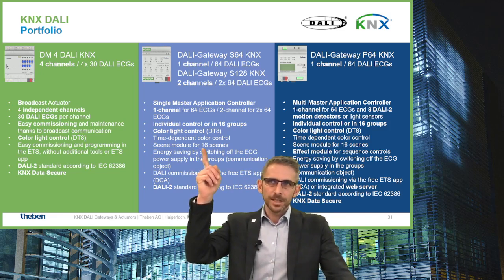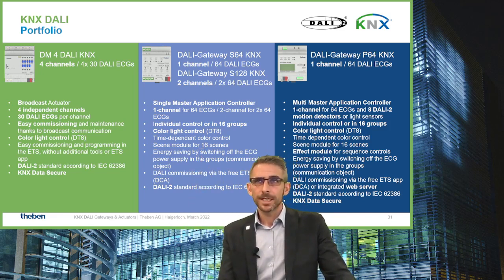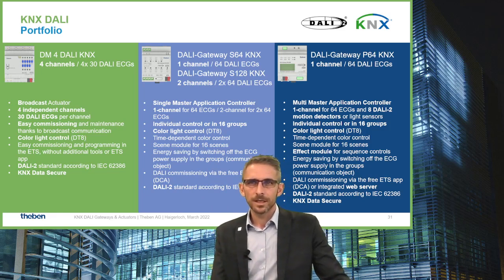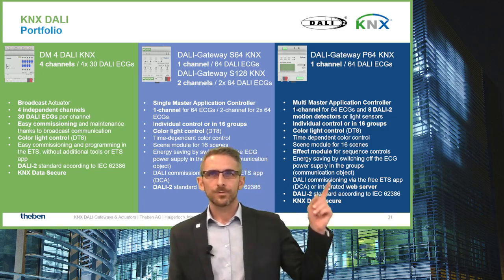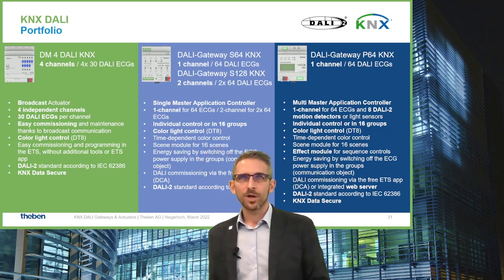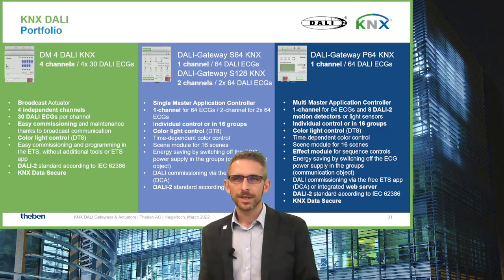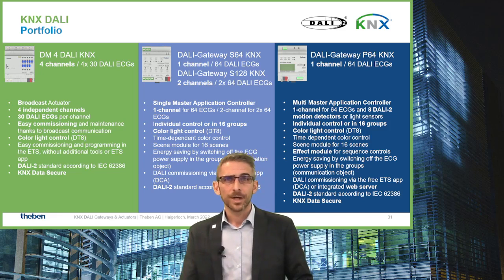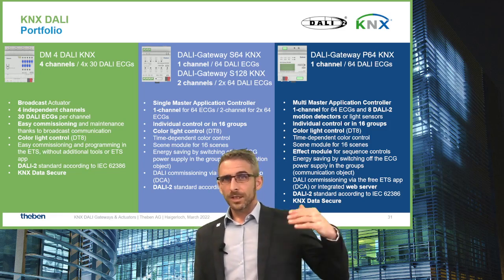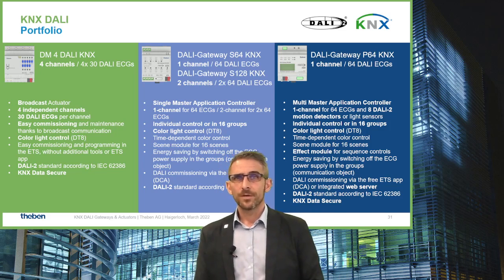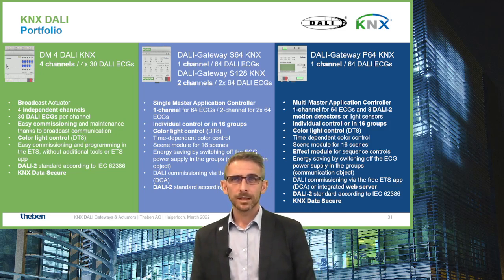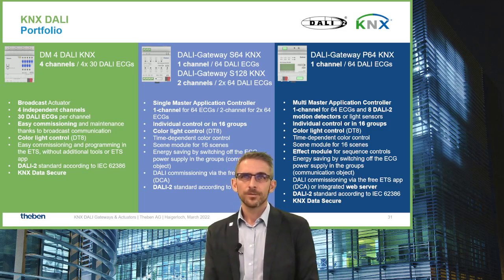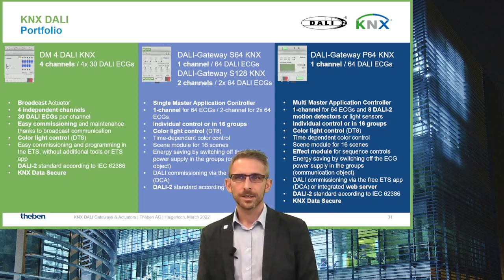Then we have talked about the functional update for the existing standard gateways, S64 and S128, which allows the individual control additionally. And we also have talked about our big block, the DALI Gateway P64, our Multimaster Application controller, and the possibility in combination with our DALI 2 sensors, which can be connected directly to the DALI line. A device with effect module, web server, so it's a very, very powerful device. And it is also supporting a secure communication following the KNX Data Secure standard.